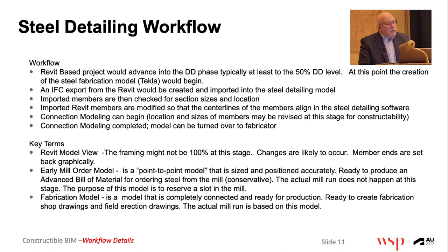Connection modeling can begin after the Tekla modelers sort out the dimensions that are lacking. Then come the constructability issues, and I'll show you on the next slide what I'm talking about. You have to sort out the RFIs that say, I can't build that. There's no room to stick your hand in and get the bolt, or it's a huge connection and you need room for it, or it's bumping into the neighboring member.